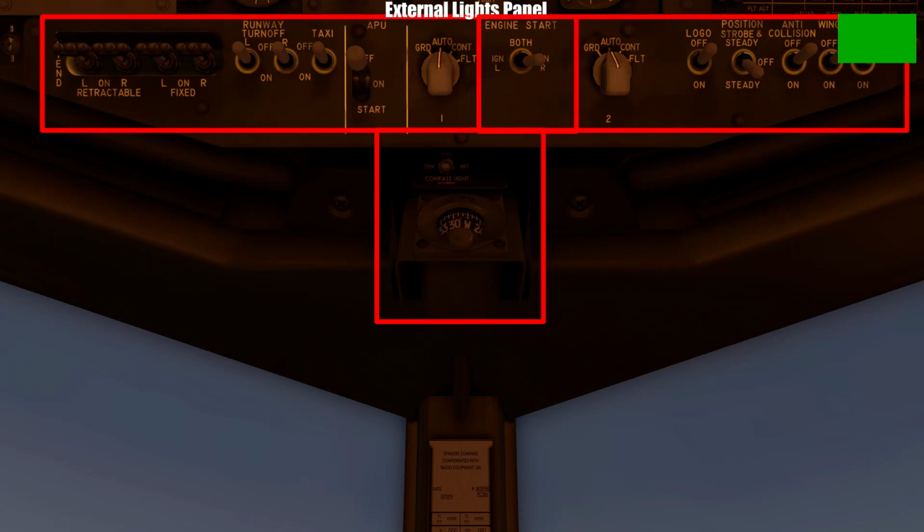In the center, we have an engine igniter switch, which pilots use to decide which engine igniters the aircraft should use to start both engines. Pilots normally never put this switch to both, and usually choose one igniter for the first flight leg and the other igniter for the return leg in order to use both igniters equally throughout the lifespan of the aircraft.